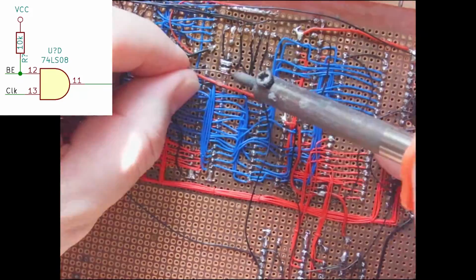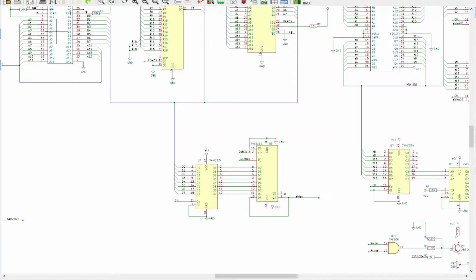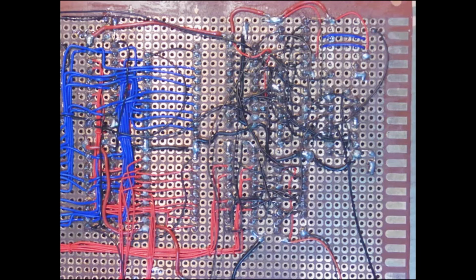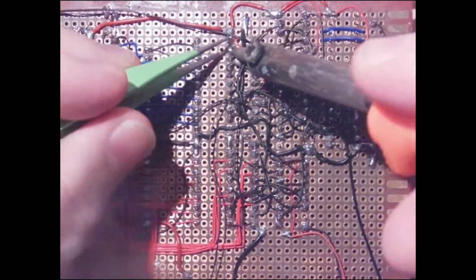Now I've copied the ROM into the RAM, and I'm going to try and display the image that's coming out of the RAM. And I got this. Here, let me play it again. After some poking around, I found out that while this flip-flop is meant to be hooked up to clock, I'd actually connected it to clock bar, so I need to correct that.